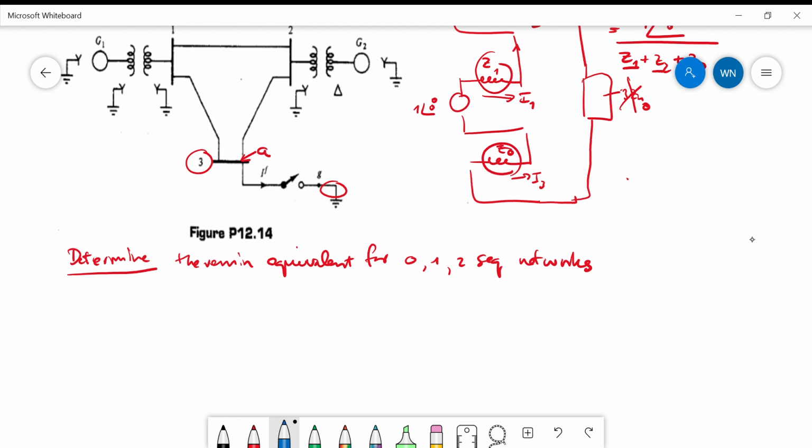Okay, this has been done quite a few times already, right? When we write the positive sequence, you have to have the voltage source, right? But later on, when you try to find the Thevenin impedance, what we have to do is deactivate the source. For simplicity, I don't want to draw everything and delete the voltage source. But what you have to know is that when we want to find the Thevenin equivalence, you have to deactivate the source. So I don't need to draw the voltage source in this case. The voltage source is represented as a short circuit, right?